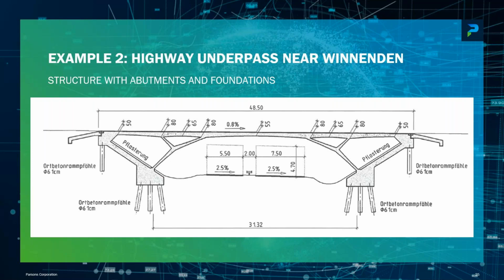So we take the horizontal thrust that we have here and bring it up to the small abutments on the top. And then we tie it together with tendons so that the concrete always sees compression, although this is a self-anchored system. And this system behaves a little bit like an inverted cable-stayed bridge, because if you put live load in the center of the span, what you will find is that the abutments want to come up because the entire system wants to rotate here around the arch support locations.